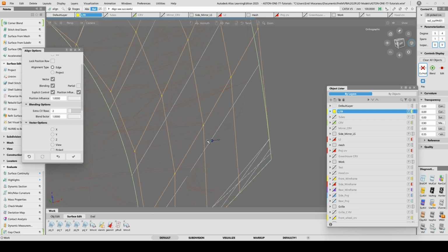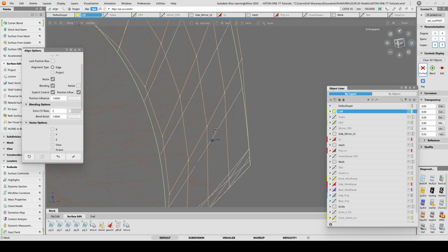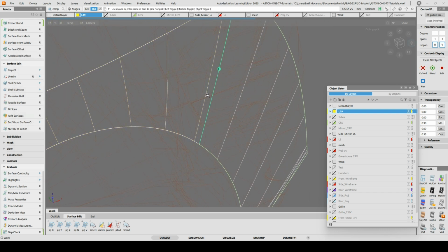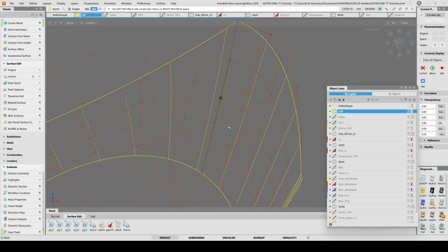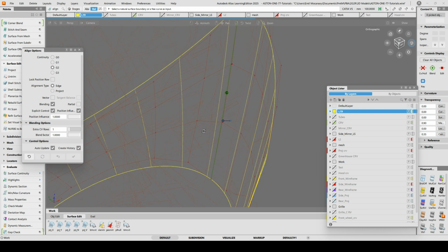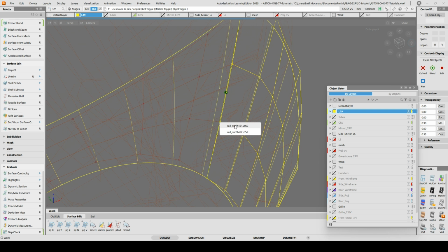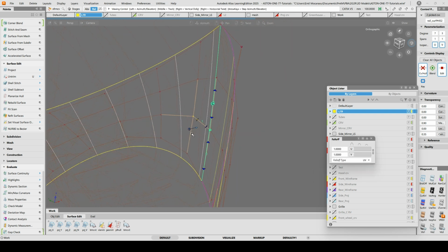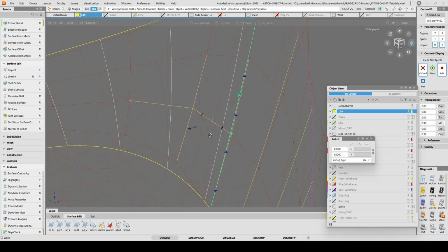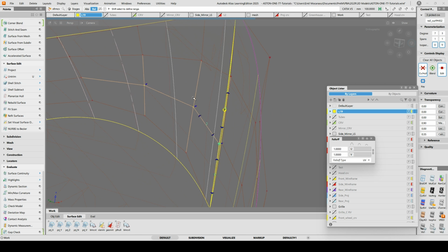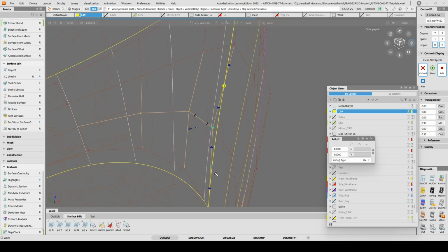And you can see here at the bottom, we're actually pretty close. So I don't want that one to change too much. So I'll bring that down to 1. And let's go ahead and work with these. Let's bring this back to degree 3. So we know we will see 1-to-1 the motion there. Now I'll take the CV move tool, proportionally modifying, as we see here it's full, while here it's already dented in, if you want to put it that way. So I'll work with that influence there a little bit, keep it to 1, start pushing these in,